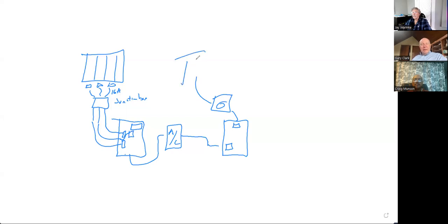So at that point, that would exceed the size of one breaker in my panel? Well, if you're running 3 of them and each one's maxing out at 60 amps, assuming you've got a 200 amp service panel with 200 amp service from the utility, it would exceed it. But if I had a 200 amp panel with 100 amp service from the utility, I could come in here with 60 amps and I'd be just fine, because I'm at 160 on a 200 amp rated bus bar.